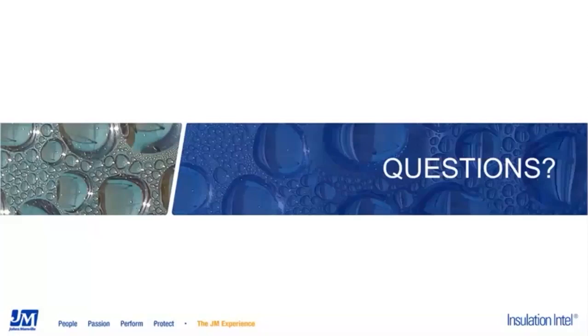If you're talking about ultra cold climates like that, you're probably concerned about freeze protection. Maybe you've got an Edmonton, Alberta sort of location where in the summer you might have to worry about condensation control and heat gain, but in the winters maybe the pipes are going to be exposed to minus 50 degrees and you have to worry about the chilled water freezing. So I think that's the way I'm going to interpret this.